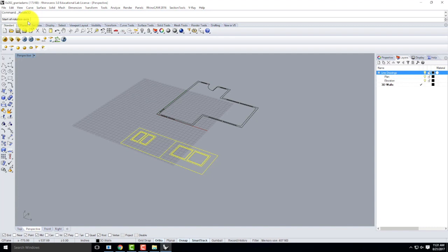So what it's telling me is, what is the start of your rotation axis? So because we're doing this in 3 dimensions, we have to think about what axis we are trying to rotate around. So you can envision this as what line. If I could draw a line in space, where is that line that I'm going to rotate around? So in this case, the line needs to happen right at the base of my building here. So my axis of rotation starts here on the building. It ends, end of rotation axis. It kind of doesn't matter. It could be somewhere off in space. But for right now, we'll end it right here on the edge of my building. Then it says angle or first reference point. So my first reference point, the easiest thing to do would be to go along this side and specify it.